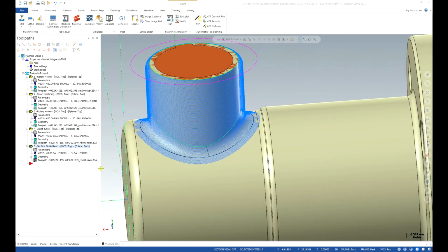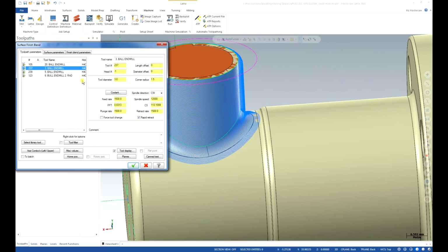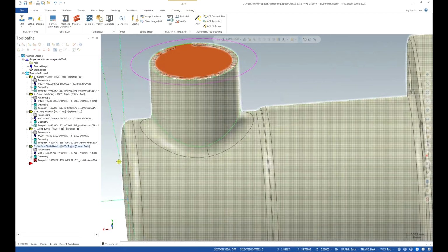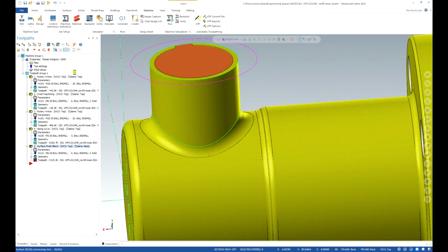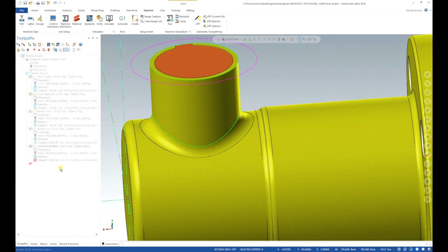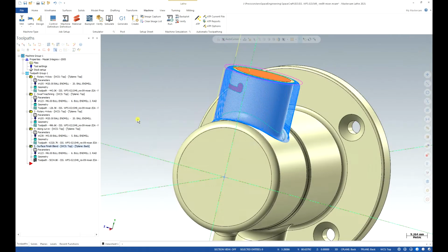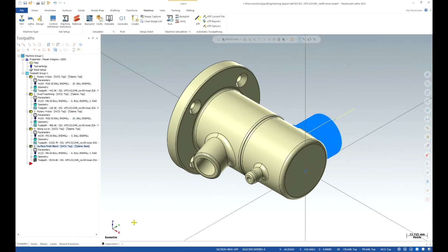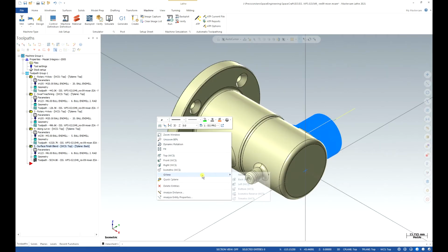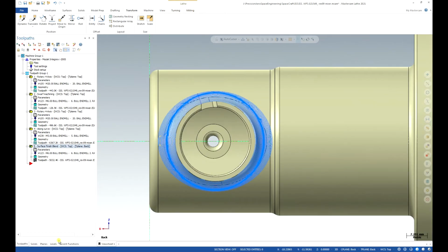Next. And in this toolpath, of course, if you want, you can use any size of the ball end mill, or even the 6mm bull nose cutter with a 2mm rad, and it will generate the toolpath as well. Let's have a look. The toolpath looks okay. We will run the simulation later. Now let's change the view to the back.